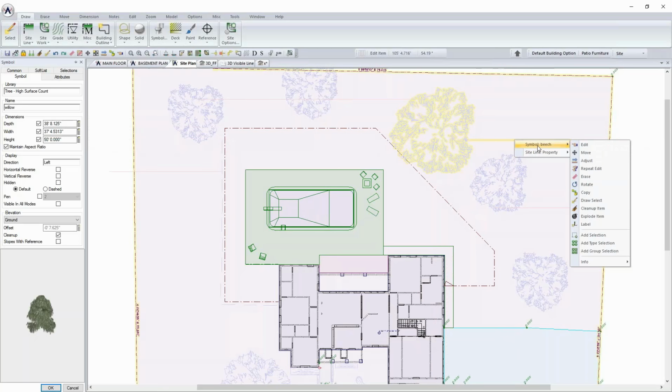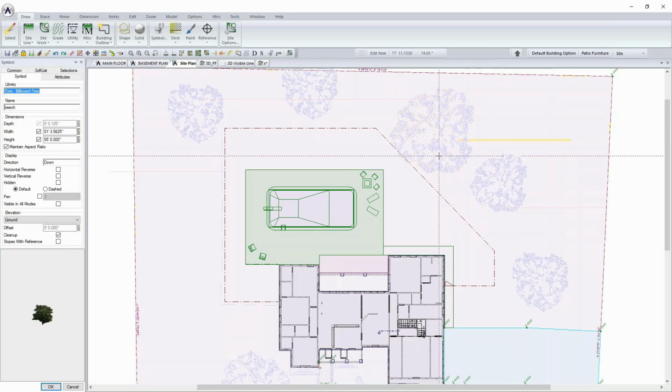The second kind of landscaping that I've got on the model for today is what's called a billboard tree. Now these tend to have a little less detail because what we're really doing is just pasting a picture of a tree onto a single plane, and then we cut out, if you will, the background on that tree. This tree has basically two surfaces, front and back, and so it regenerates much faster as opposed to a tree over here, which may, arbitrarily say, have several hundred surfaces on it. And so as you can see, I could draw 200 of these trees to equal one of these trees in terms of surfaces, for example.